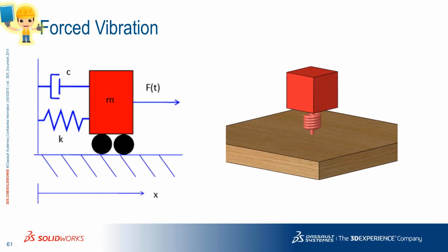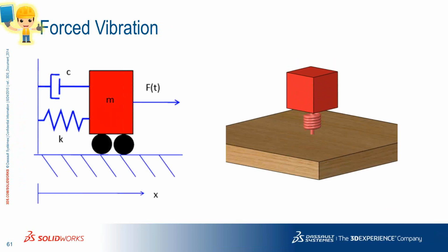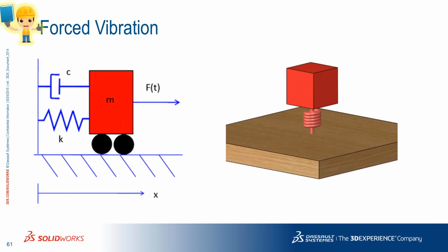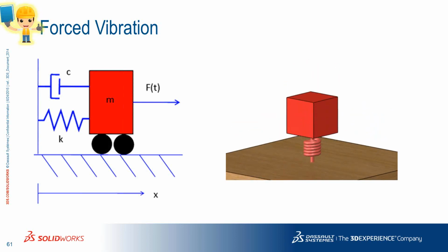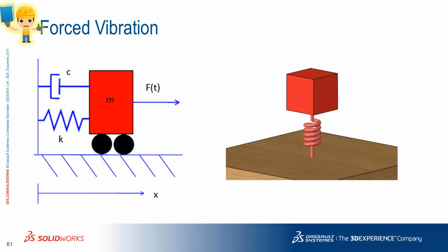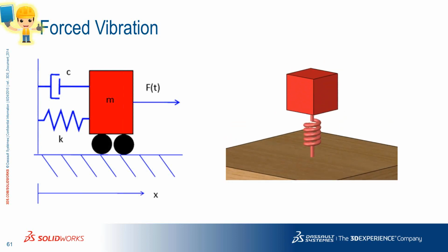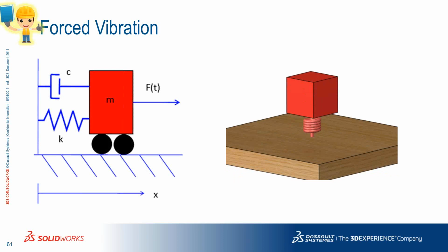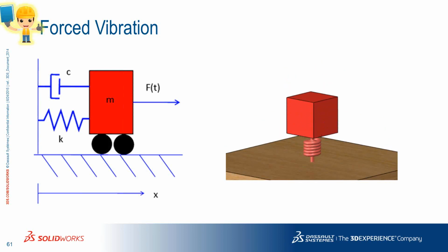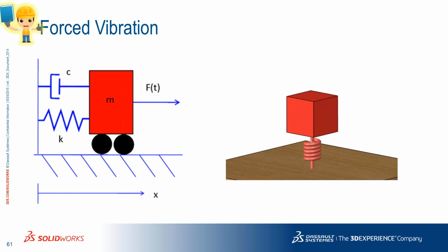I'm going to skip the slide, but think about frequency analysis as free vibration, and what we're going to try to do next is true vibration analysis. We call that forced vibration. Hopefully this particular slide showing the animation gives you an idea of what we mean by forced vibration. You might be testing your designs today according to a build spec where you are mounting the product onto a shaker bed table, and the table shakes up and down or sideways over several excitation frequencies. That's the exact scenario that we are going to simulate using SOLIDWORKS Simulation.